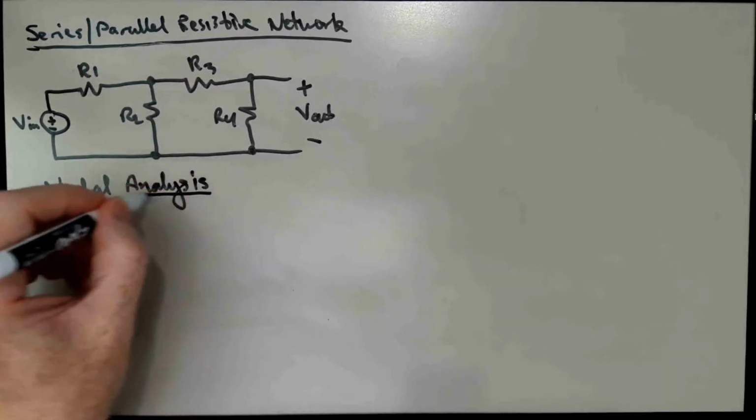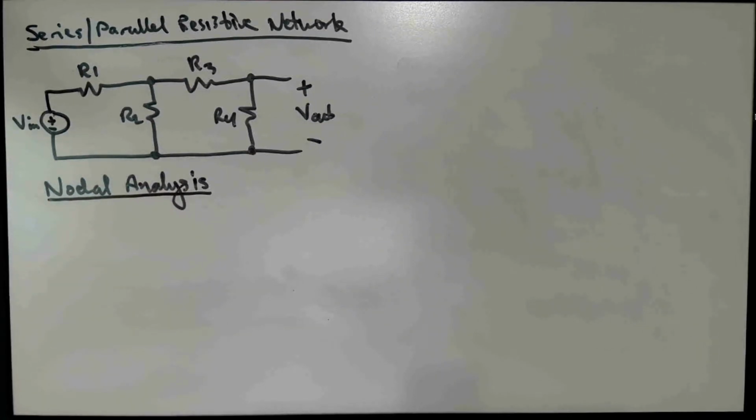And nodal analysis is a generally applicable method of analyzing any linear network, and it's very powerful, and it's very good for doing things like proving theorems that hold in general about general networks. It's very good if you're writing a circuit simulator like SPICE that's going to systematically solve the circuit equations that you feed in to it.